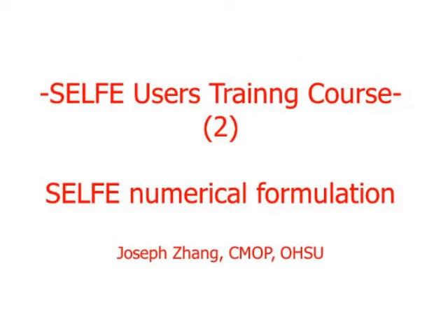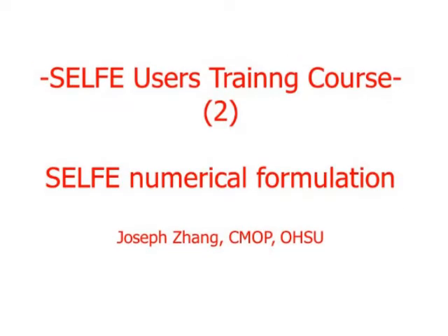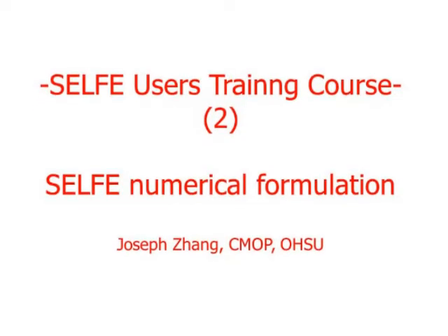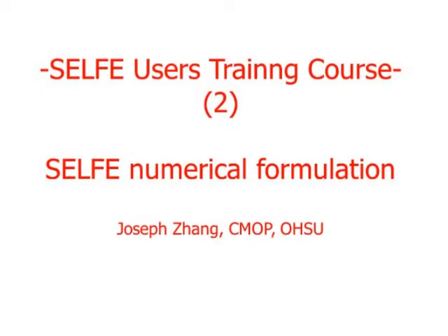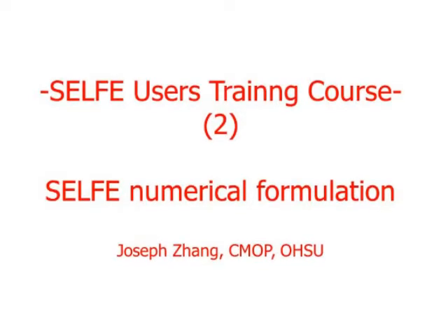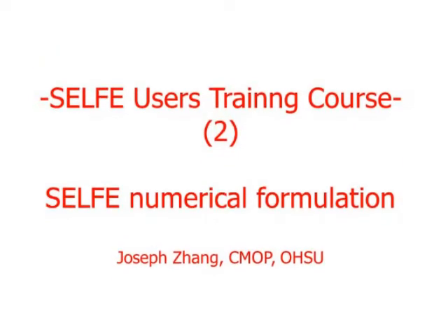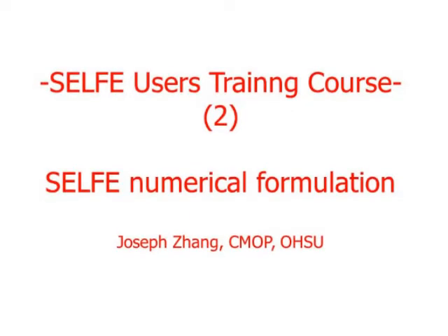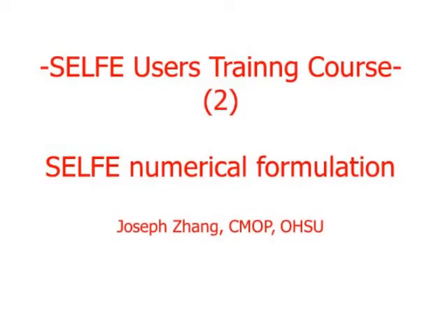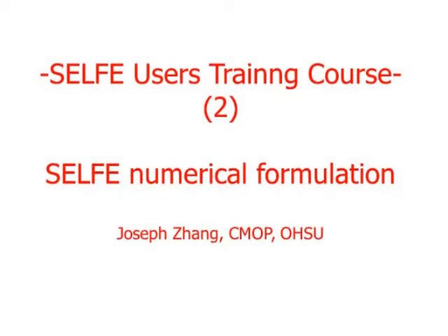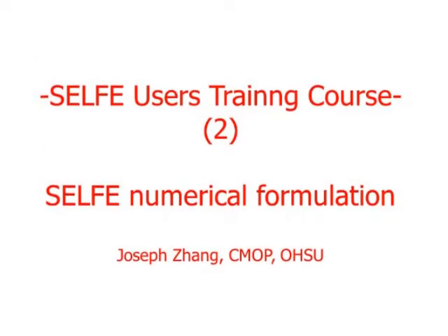Alpha is the Shapiro factor, and people have proved, at least for the uniform grid, that alpha equals 0.5 is best in the sense that it filters out all the subgrid noise, whereas it leaves the physical signal untouched. So we typically just use alpha equals 0.5.